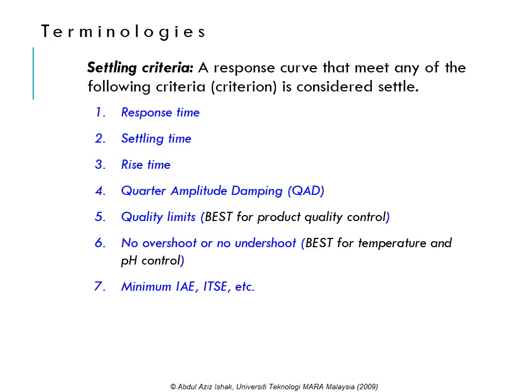Some might be looking for fast response with minimum time delay. Some, on the other hand, might look for longer settling time, as some processes require some time to achieve complete conversion. Others, for example, look for faster rise time. The response curve must be in quarter amplitude damping, for example, type of response.